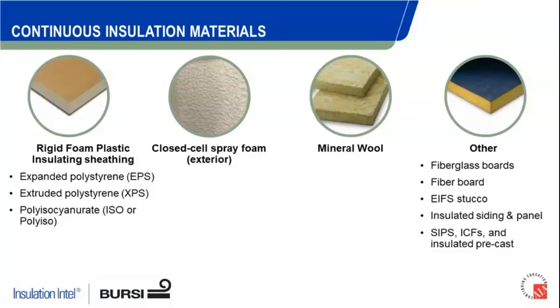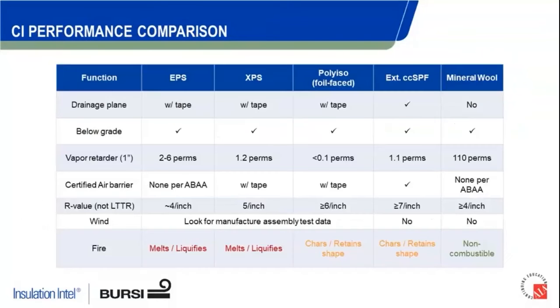Structural insulated wall panels, insulated concrete forms, again, kind of specialized systems that do incorporate some level of continuous insulation into them. So breaking down here in this case, the most common performance criteria that we're often looking at when we're trying to decide on one material or the other.